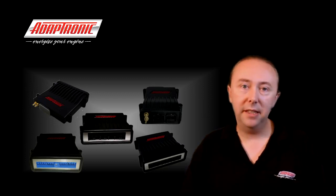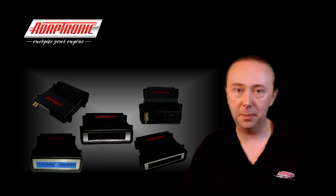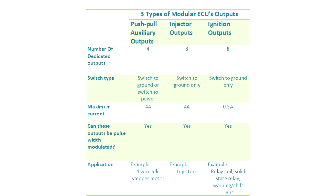Most auxiliary outputs on ECUs switch to ground, with the other side of the load needing to be connected to a 12 volt supply. This is because of the way transistors are made. Switching to ground is a lot cheaper and easier. Modular ECUs have three types of outputs.